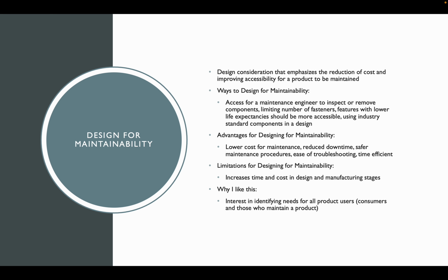Ways to design for maintainability can be to improve access for a maintenance engineer to inspect or remove components, limiting the number of fasteners in a design, making features with lower life expectancies more accessible to somebody to look at them, and using industry standard components in a design.